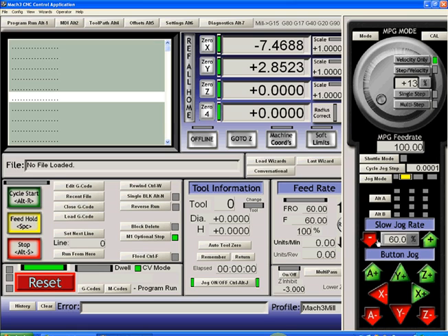It can also do other sharp features like shuttle mode, which allows you to run a program while rotating the wheel. The program actually runs at the speed that you rotate your MPG. You'll notice when I selected shuttle mode, our jog mode went over to MPG mode. Turning off jog mode, and we'll go back to the normal jog. So if you look at this screen, the second LED here should be lit, indicating that you're in normal keyboard jog mode, and you should have a jog speed above 5%, and you should see movement.